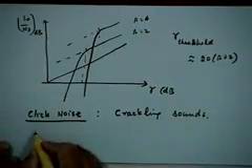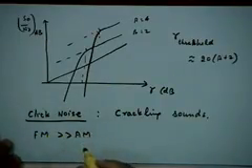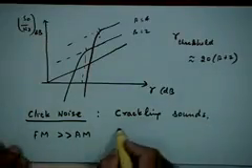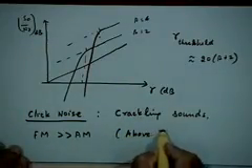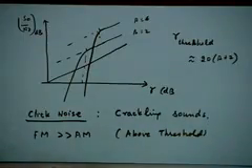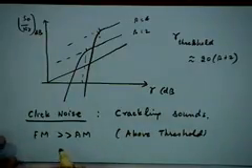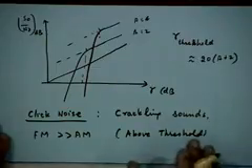So we have to therefore keep in mind that while FM in general is much superior to AM above threshold, it can become very bad below the threshold region, right? So you have to keep the input SNR at a significantly good level so that you are above the threshold region. Okay.